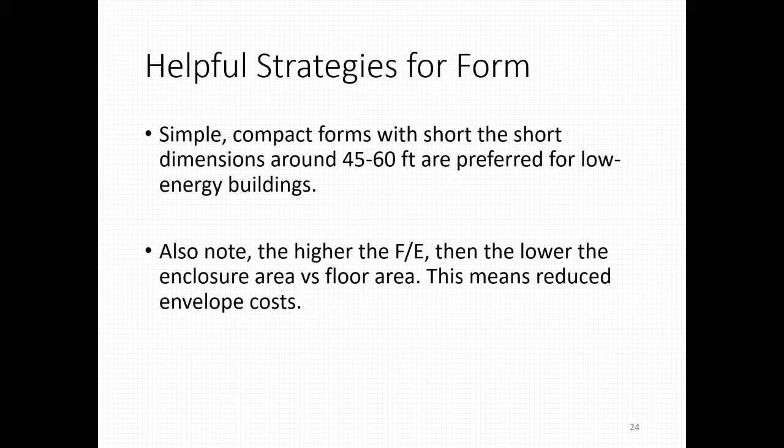So, when you have this type of layout, you can reduce the lighting loads in your building. And these occur mostly during the day when your building's occupied, in commercial. So, if I can use free light in my building, I can cut down on my lighting costs per square foot, the amount of energy that I need to use in my building, and the amount of lighting equipment.